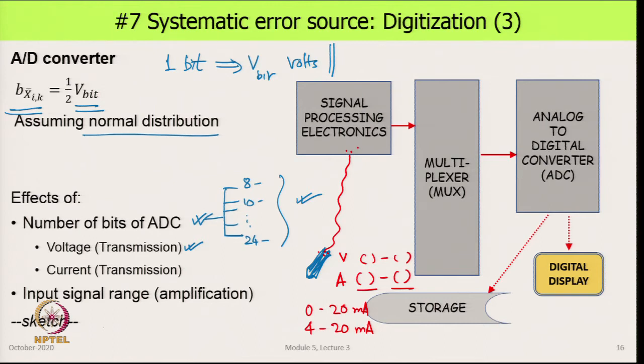So, the instrument itself has certain electronics in there, where it may take a voltage as a sensing signal, convert it into a corresponding current signal over a range and output it in the wire. And so, what happens is the same current is coming to the processing electronics, where you pass that current over a resistor and you then input the voltage value to the signal processing.